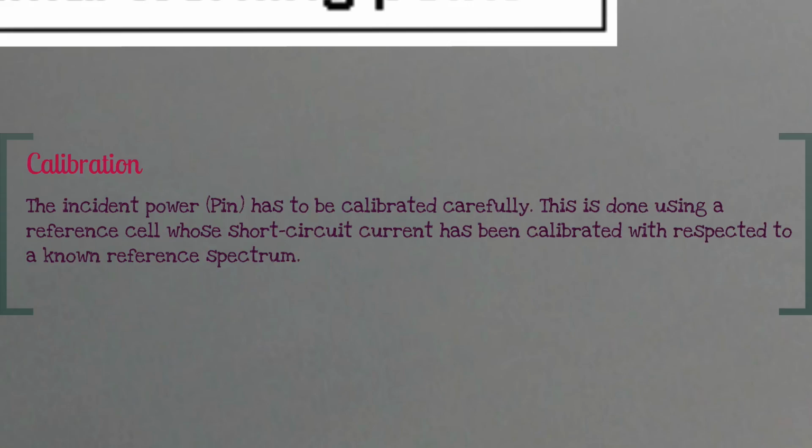Now, calibration is also quite important, primarily because the incident power, or the insolation, the denominator of the efficiency, cannot be measured very precisely unless you have very expensive equipment. To avoid this, if you're installing it on a roof, someone doesn't have to bring expensive equipment; you can use a reference cell. This reference cell is basically a photodetector, usually a silicon solar cell also, which is calibrated very carefully such that its reading corresponds to the exact measurement.